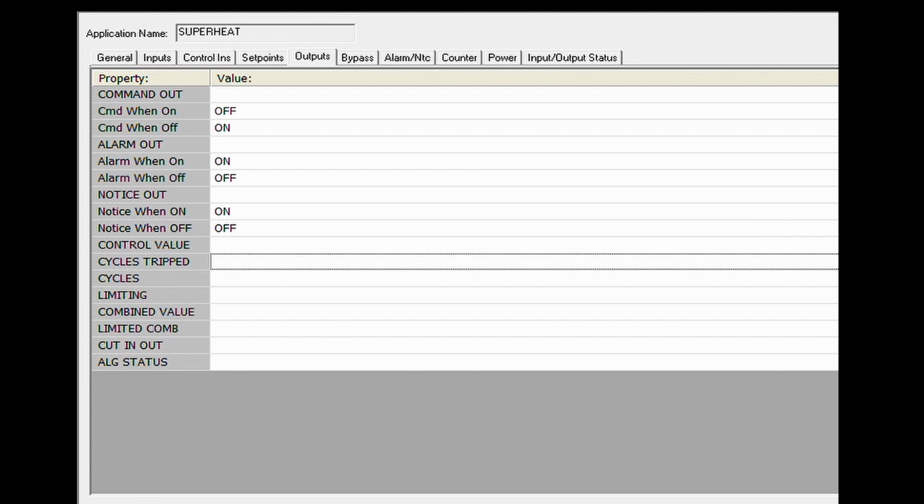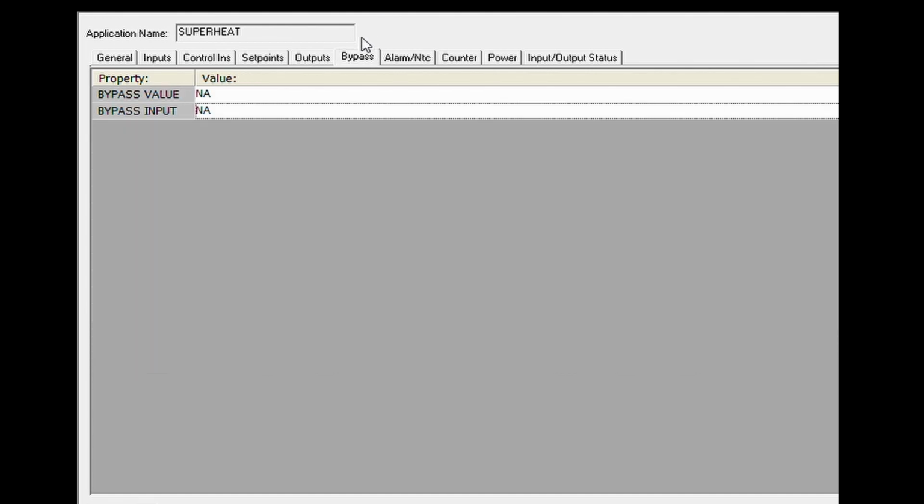So now see how it's got this graph next to it? That's the logging setup. So each time you set up a point, like an input or an output, please set up logging, because the guy that comes behind you that tries to troubleshoot this won't have any logging, and it's going to be a royal pain.